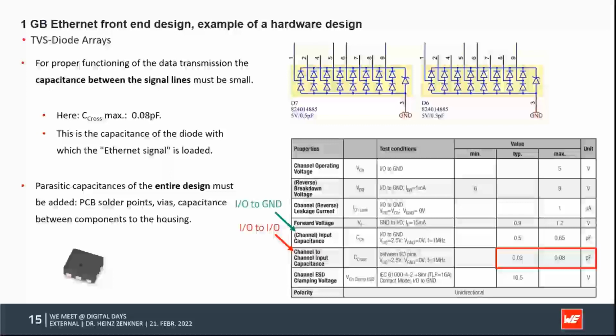If you don't have a sufficient ground directly to your Ethernet controller, if there's, for example, a long trace, too long a distance, you can imagine with this low capacitance, any nanohenry you have here will cause ringing, will cause impedances, which then make it almost impossible to clamp the fast transients sufficiently to have sufficient protection for the controller.